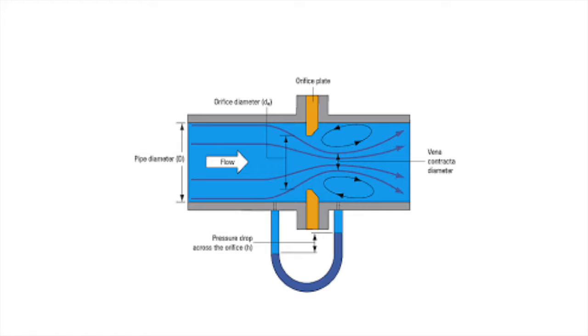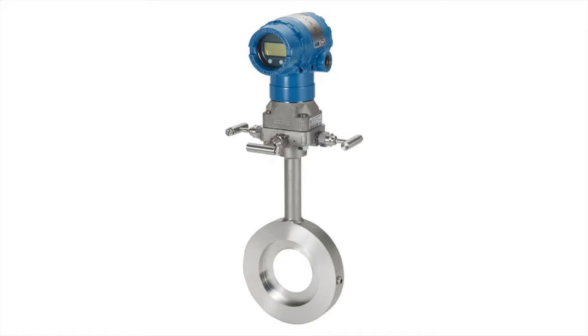An orifice plate flow meter is a flat plate with a hole in the center that is placed in between flanges in a pipeline across the flow of a liquid. The pressure difference generated by the flow velocity through the hole enables the flow quantity to be measured. These meters measure gas, liquid, or steam in commercial or industrial situations.